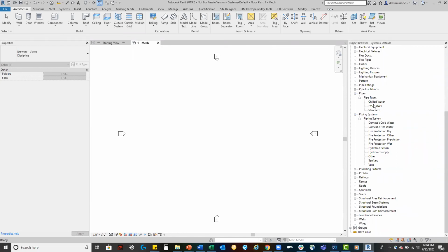In Revit, to use pipes properly, your pipe types are the physical materials that create the pipe. So copper K, copper L, copper M, PVC, domestic waste and vent, CPVC, ABS, whatever types of pipes you're trying to make. Of course, copper K, copper L, copper M can carry wide variants of a system inside of it. And so that is how Revit is intended to be used.